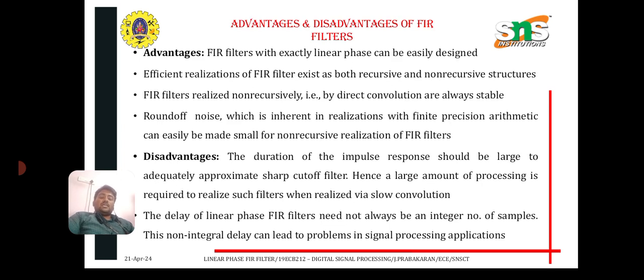Here we can see the advantages and disadvantages of FIR filters. Advantages of FIR filter: exactly linear phase can be easily designed. Efficient realization of FIR filter exists as both recursive and non-recursive structures. FIR filters realized non-recursively by direct convolution are always stable. Round-off noise, which is inherent in realization with finite precision arithmetic, can easily be made small for non-recursive realization of FIR filters.